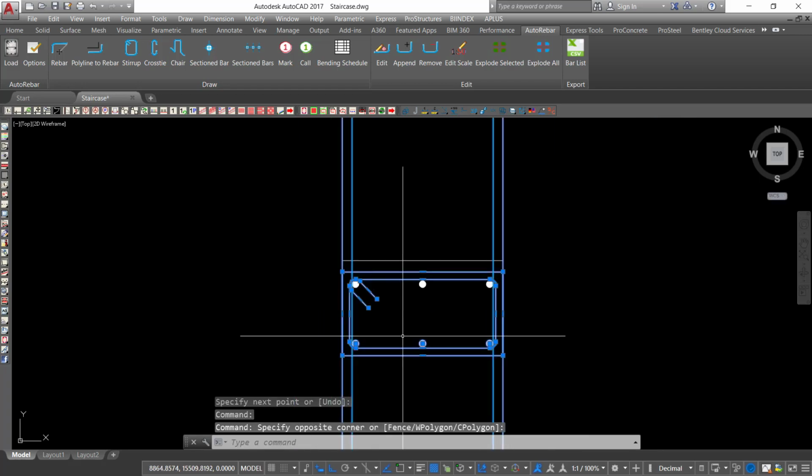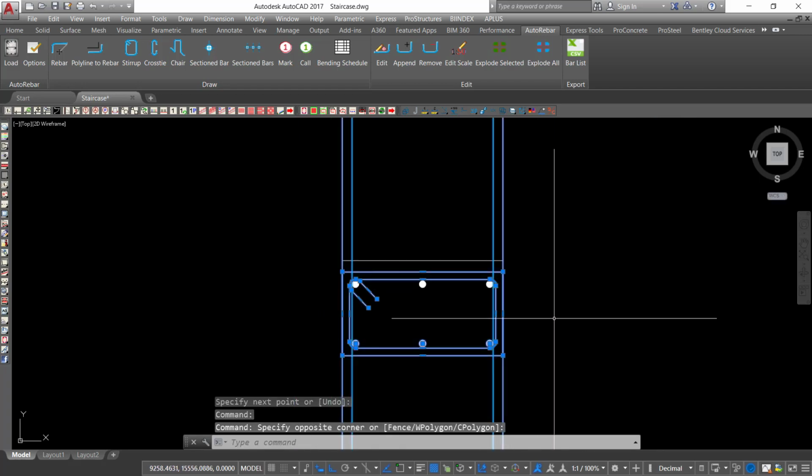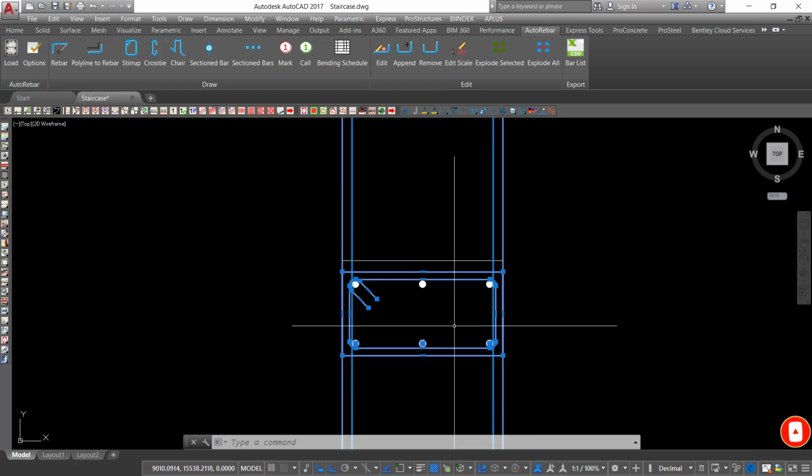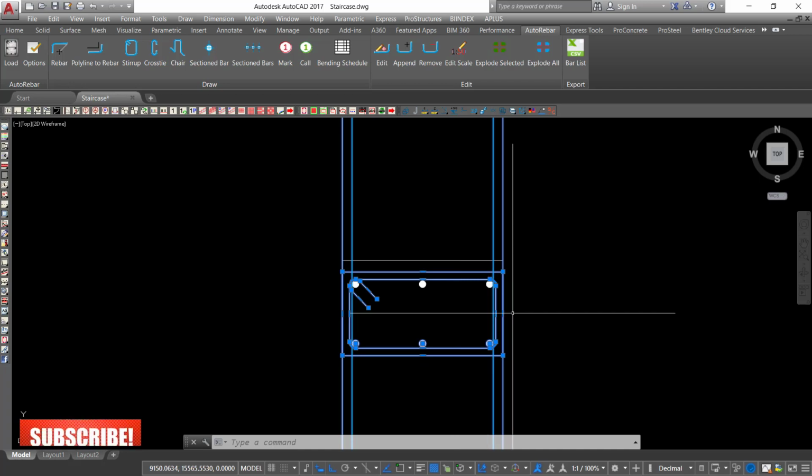So this is a column and there's a column next to it. In between, the gap will be filled with the masonry blocks, and at the top of this beam we'll lay a DPC, a damp-proof element that will block the moisture entry to the masonry bricks. Now let me escape that.